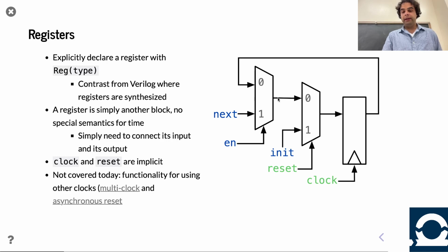And is that all? Well, we could have wired it directly to the register, but instead we have this additional portion in between. We have the possibility of a reset. So if reset is true, instead of taking whatever value we want to put in the register from the next signal or even the prior signal, it doesn't matter, this initial value is put in there. No matter what, that's the reset. So this is just a reminder that in the register, we have this notion of a write enable, which controls whether or not we change values, and this reset, which controls the ability to set to a known value no matter what. And not every register has all these pieces always, but I'm just reminding you what they are.